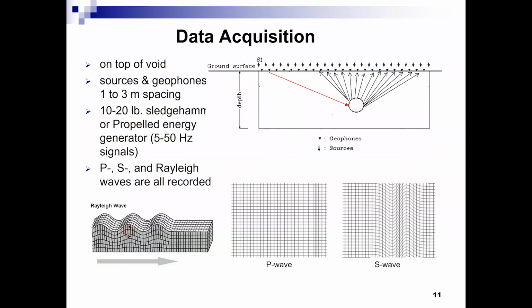Does that mean you would like to use high frequencies, because that would suppress the Rayleigh wave at deeper depths? In other words, high frequency short wave Rayleigh waves would be suppressed at deeper measurement points, and just body waves would be sampling that material?